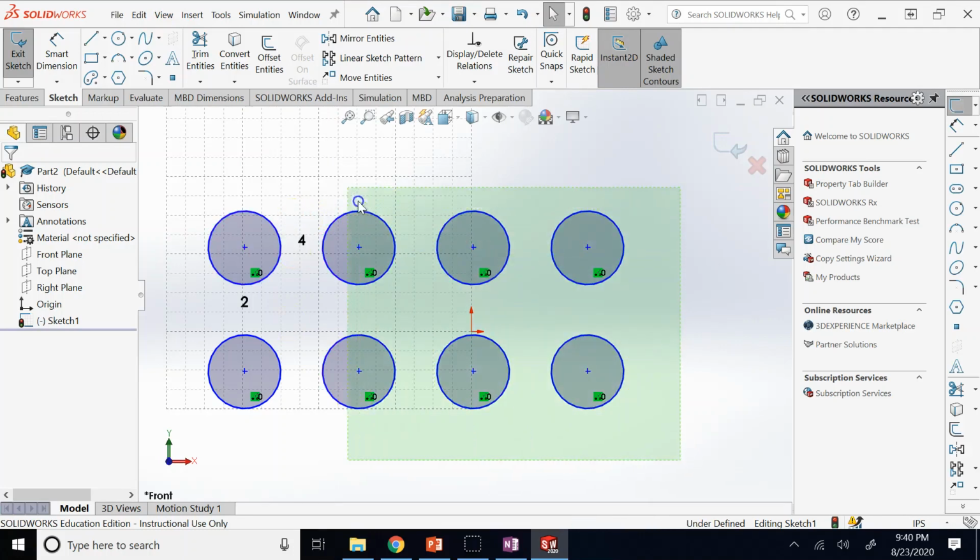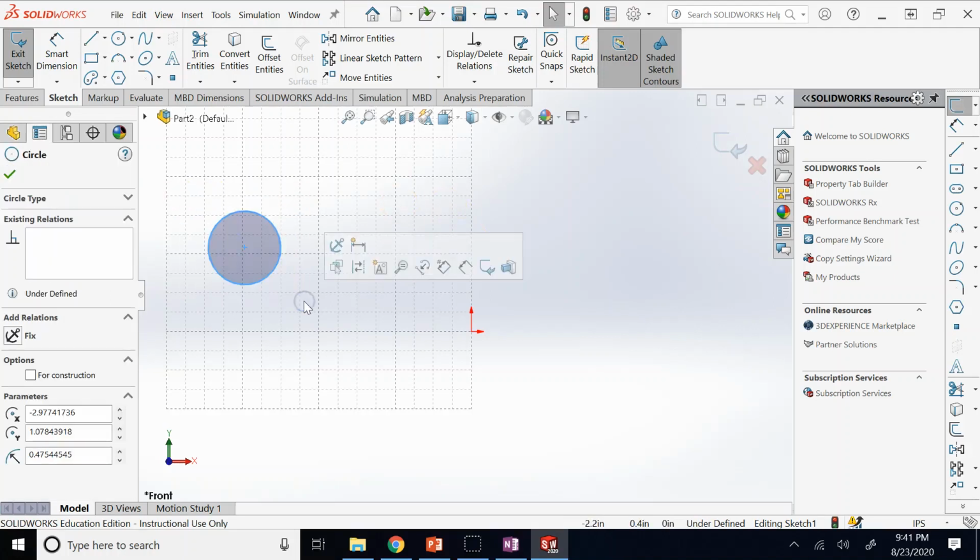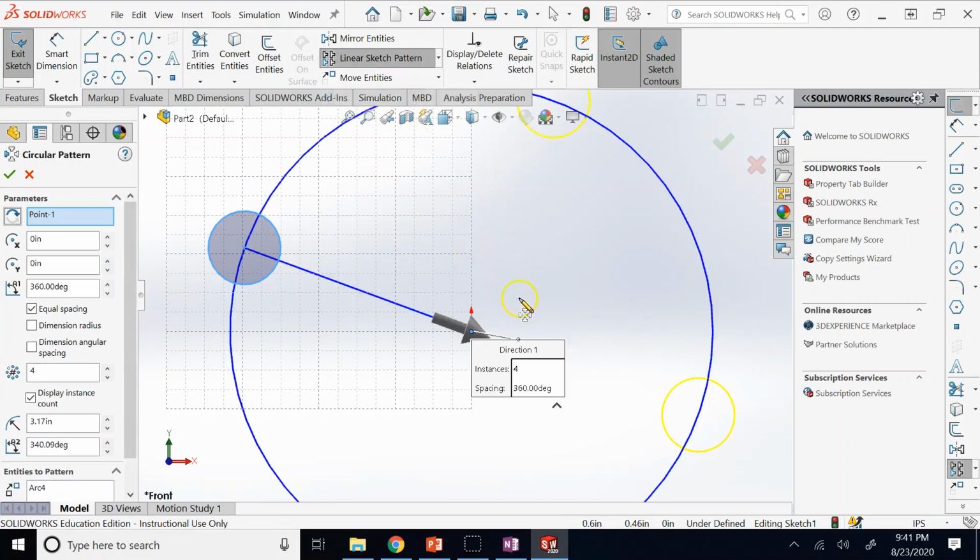The other thing you can do is called a circular pattern. So you can basically pattern a sketch about a point. So I want this to be repeated in a circular manner. About, you need to have a reference point, and here the only point that is available right now is origin, but you can draw ahead of time another point and then rotate it about that point.